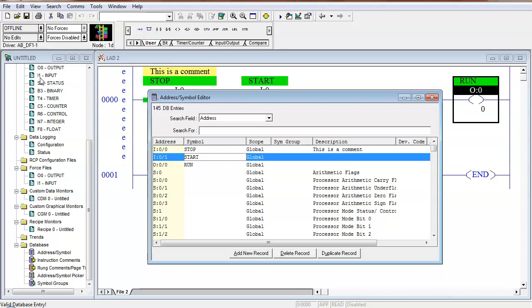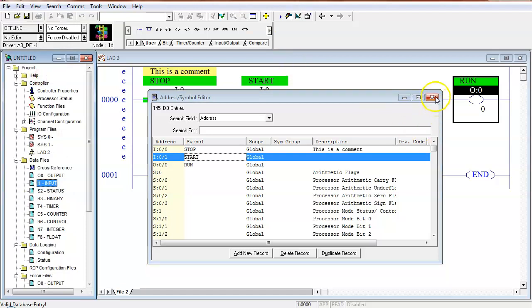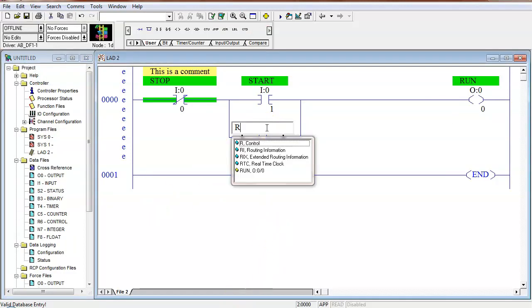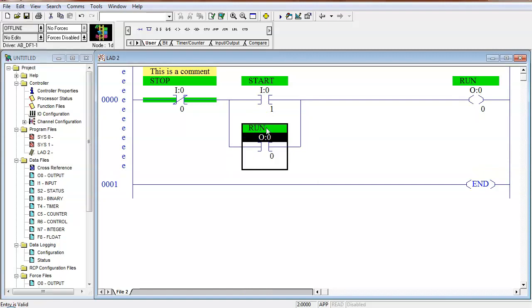What I've done, down there on your PLC, you have a switch labeled what? 0. So I've connected that symbol to that switch. Okay. Now down here, I'm just going to type in run, because I've already assigned it a symbol. So when this output goes true, this internal contact that's not even real, it's a program, is going to close.